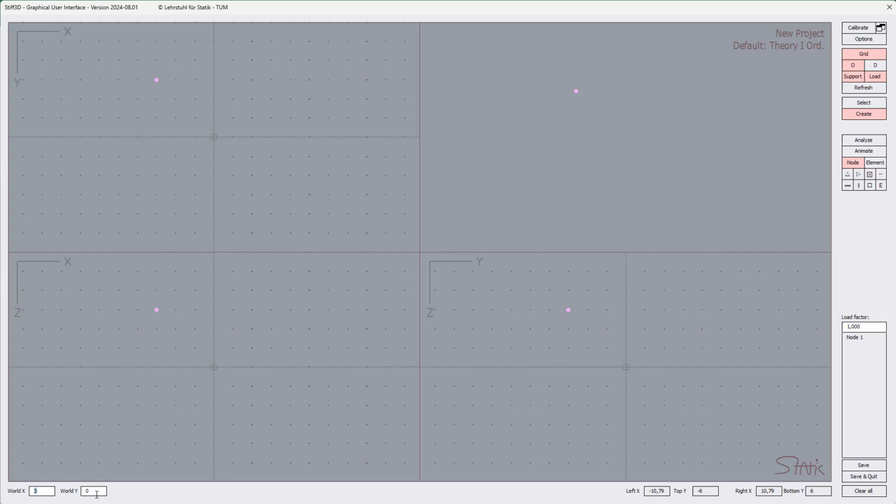And again tab, you see the display has been changed here now to World X and here to World Y. We can now again press the tab key, and we come to World Y, and let's choose it again to be -3, return, and voila, we have now generated our second node. Here we have the bottom now displayed, which is of course the same as the top level, the roof level, because still nothing has been generated in that direction.